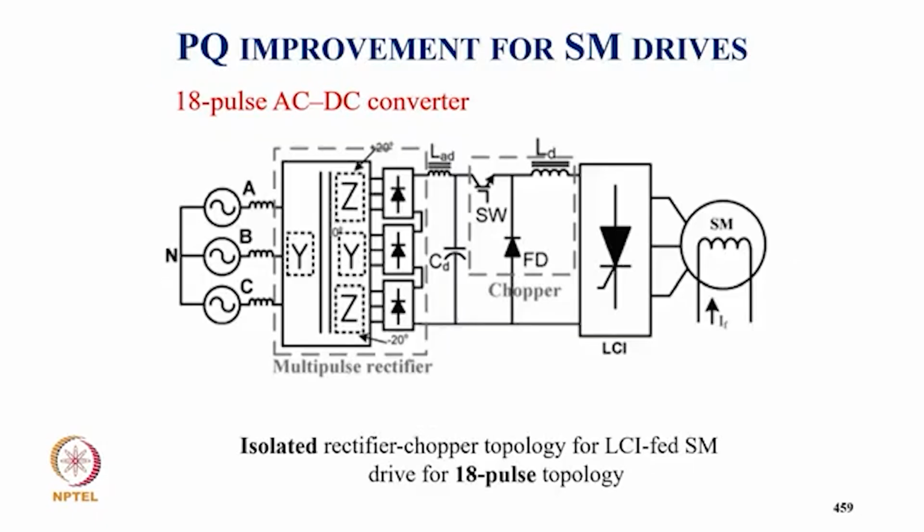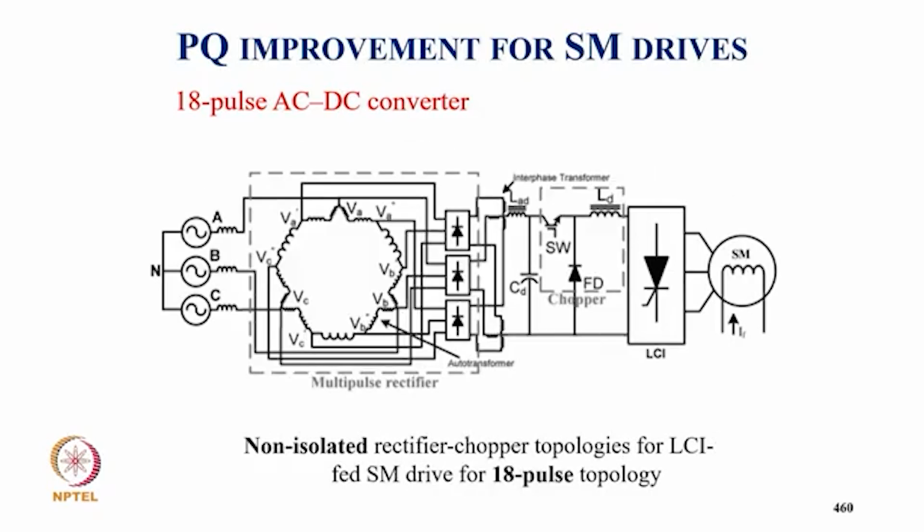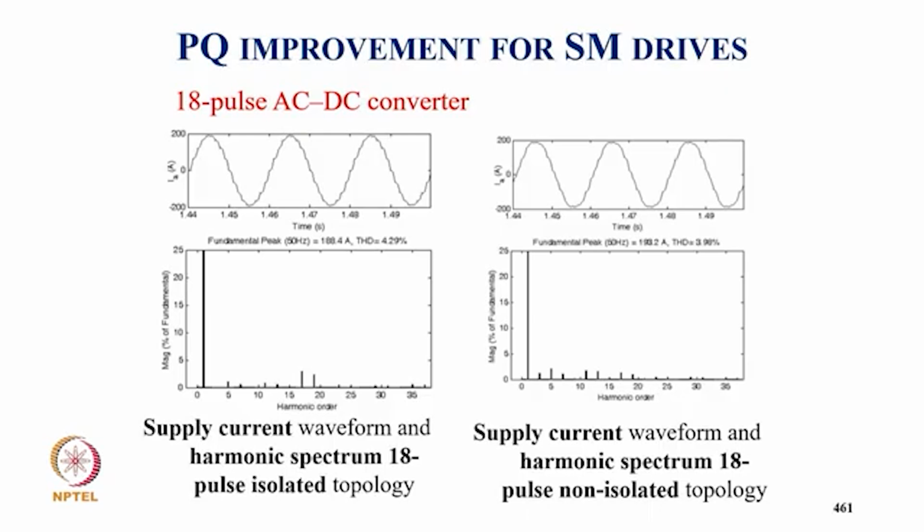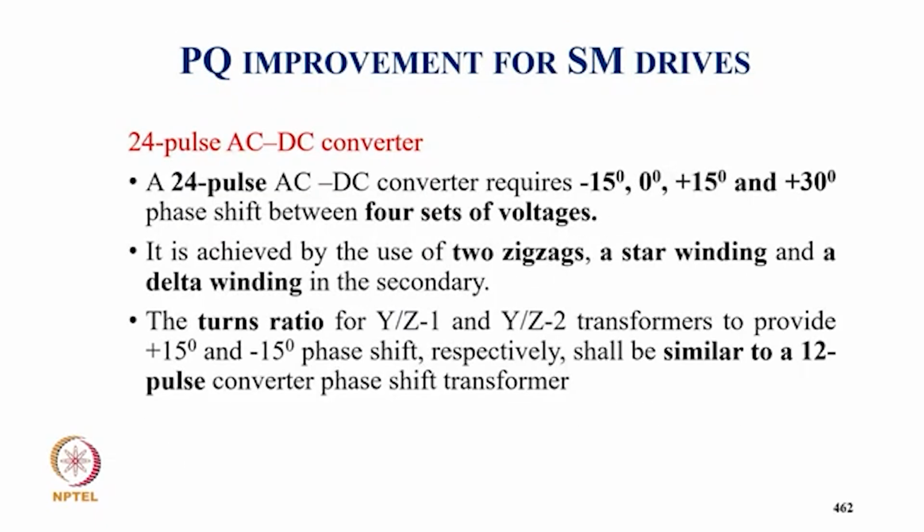And this is typically an 18 pulse converter with the diode rectifier and the buck converter feeding the LC filter to drive the current source. And this is another configuration of a typical 18 pulse topology with the buck converter, and the THD here is considered less than 5%. You can see at light load as well, for both isolated and non-isolated topologies.